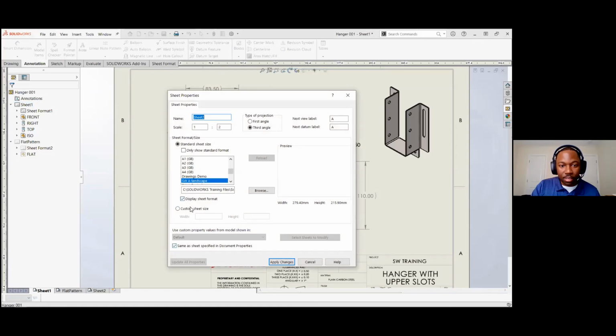So is there a way to have the font auto resize to fit in the title block? There's one option, was it fit text? It's not that the text box gets bigger. If you've got a fixed amount in your title block cell, you can have it scale to fit, though there's a limit to how much you can still stick in that one little box. That's how I would do it.